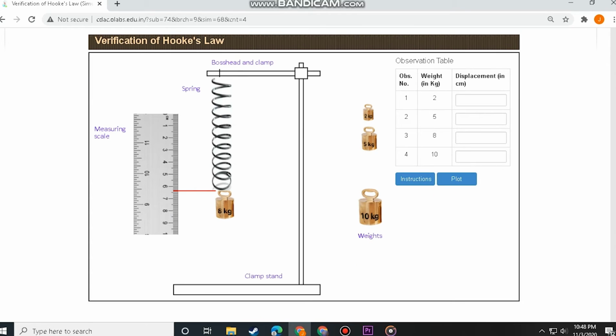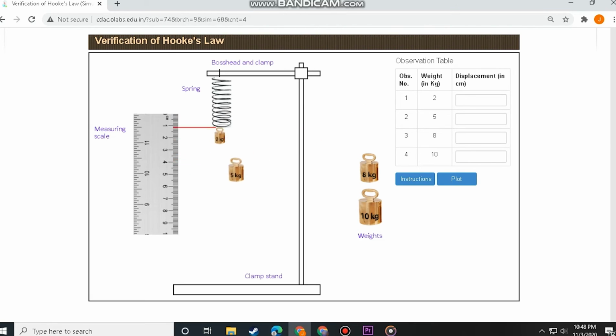So after recording in table 7.1 the pointer position that corresponds to the 3 kilogram mass loaded on the spring, gradually reduce the load in increments of 3 kilograms, duly recording the resulting position of the pointer each time. Take note, the mass in table 7.2 corresponds to the mass unloaded from the spring.